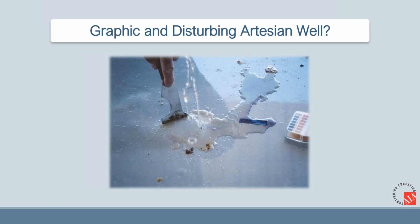Well, obviously they didn't put a barrier under the concrete, and that's water coming up from the soil, or water from a high water table is leaching up into the concrete. The other response I get a lot is there's a broken water pipe underneath the slab, or there's a flood that was outside from rains, or landscape that was sloped back towards a building, worked its way under the foundations. The reality is this phenomenon actually took place in a third floor pan deck at a clean room.